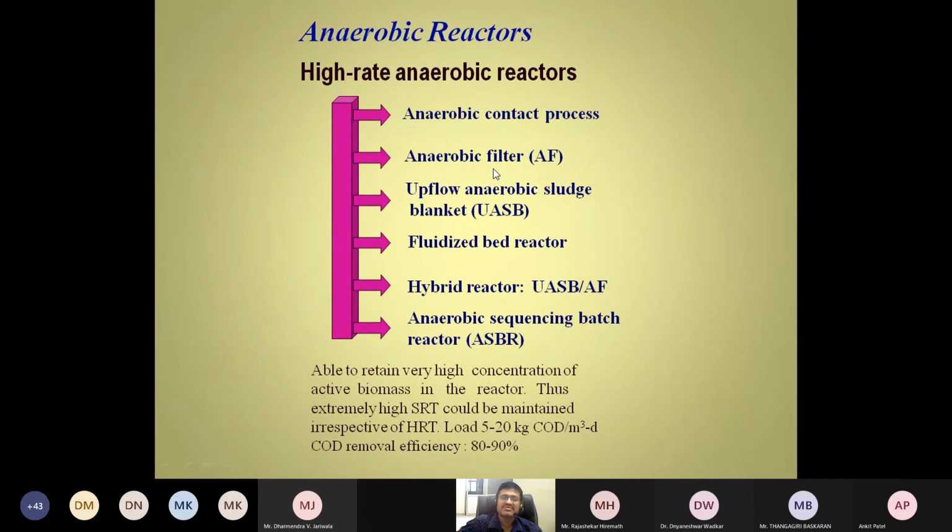So for that type of effluent, we have to use anaerobic treatment. Why? No oxygen or air is required. What you have to do is just cover the reactor, mix it properly, give some input like anaerobic bacteria to start it, and then monitor it properly. Why do we have to monitor it?